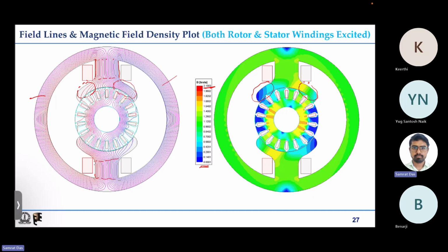If you compare with the flux density in the stator pole main body, which is green, probably 1.2 Tesla here, you see it is going into yellow also, and yellow is higher than green. So you have higher flux density on one side of the stator pole shoe compared to even the main body or the stator yoke. So that is one observation you can make.